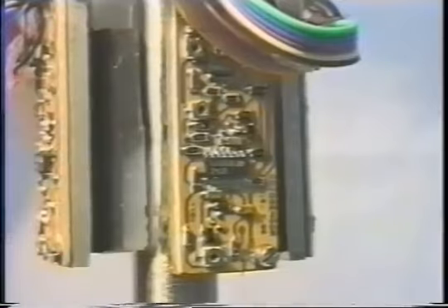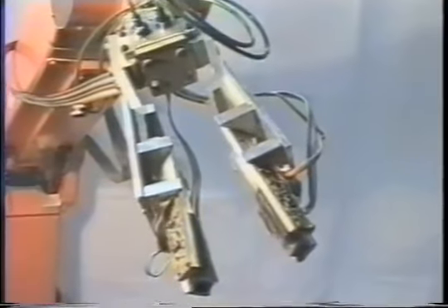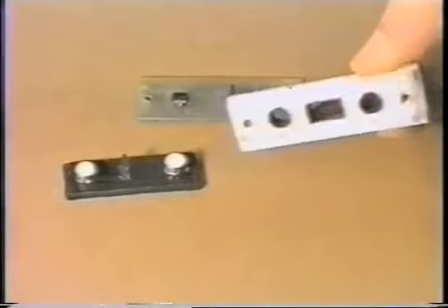New soft textile sensors using reflection optocouplers as the basic sensing elements are developed. Two pairs of sensors surround the object and detect its movement caused by the external forces. Complete sensor consists of three main parts. Upper rigid plate carries soft rubber on one side and white reflective surfaces on the other. There is the sensor's elastic body made of silicon rubber on the lower rigid plate.